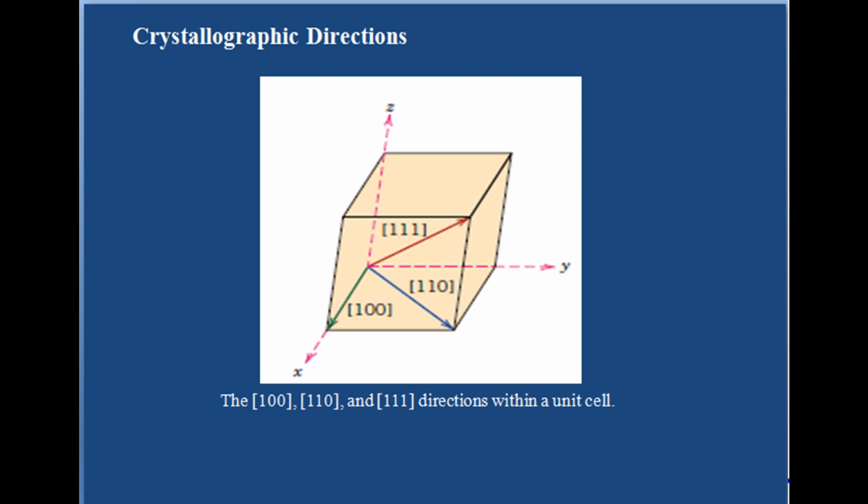Now we will proceed further with the next point, that is crystallographic directions. A crystallographic direction is defined as a line between 2 points, or a vector. The following steps are used to determine the three directional indices. First, a vector of convenient length is positioned such that it passes through the origin of the coordinate system. Any vector may be translated throughout the crystal lattice without alteration if parallelism is maintained. This is our first step.